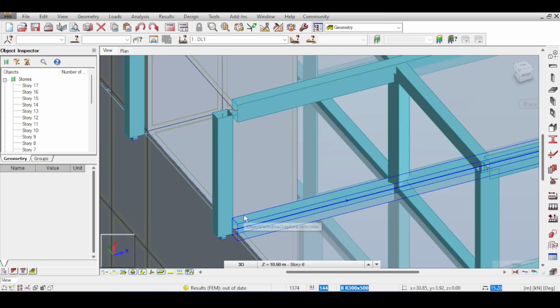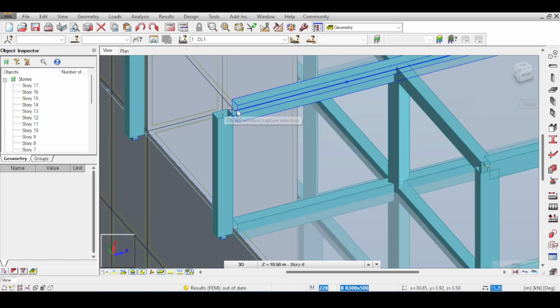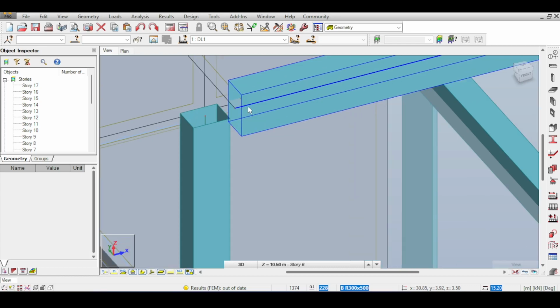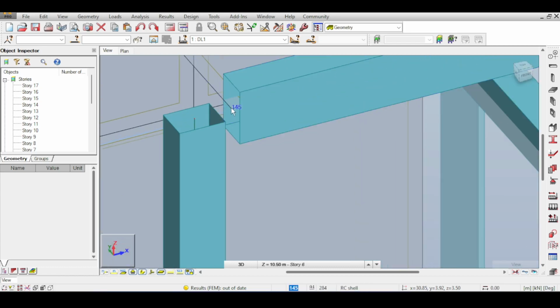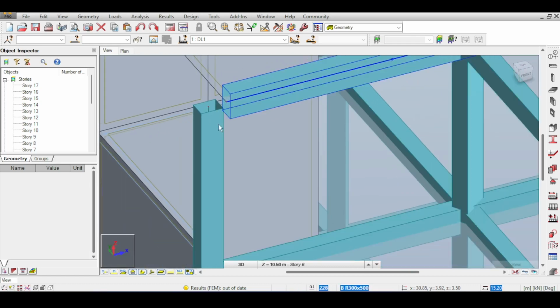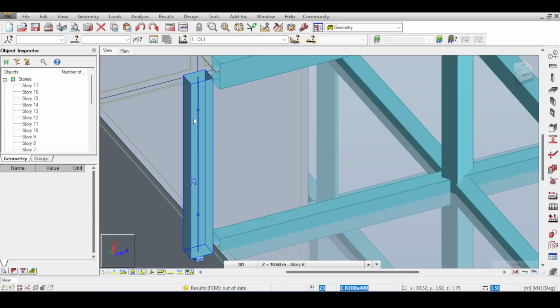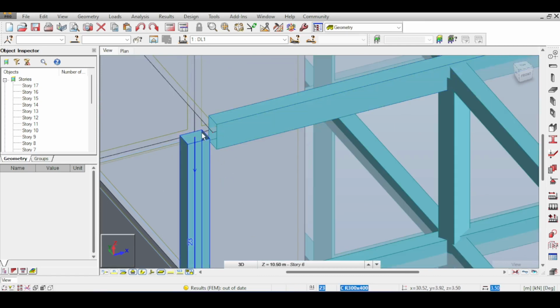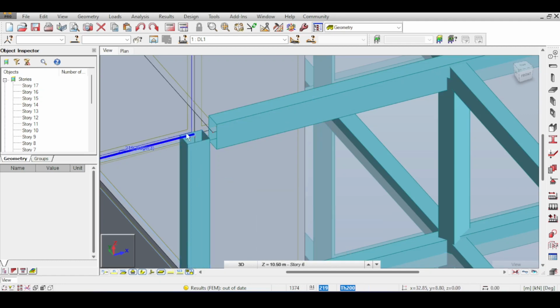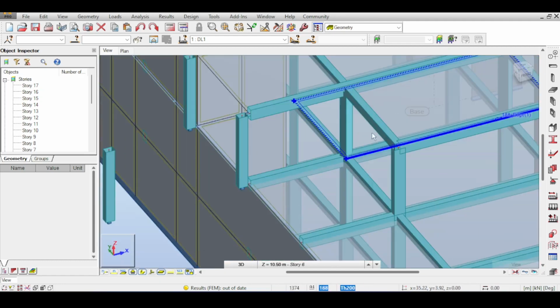If I add a column, I would add it at the node, because that's what the finite element method wants from me. And of course, I am having a finite element series, so anybody who is watching that knows exactly why I should have a column connecting to this node. Now, the problem is, if I connect the column to this node, graphically, you will see the two columns intersect, whereas in reality, they should not. Having them graphically intersect doesn't matter as long as the columns are not connected, so that's okay. I will just do it.